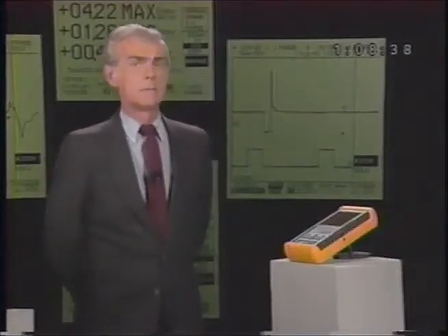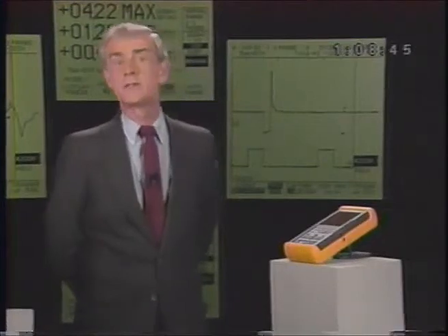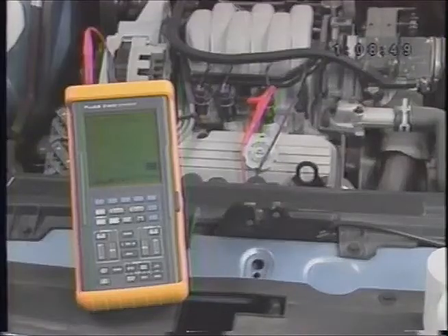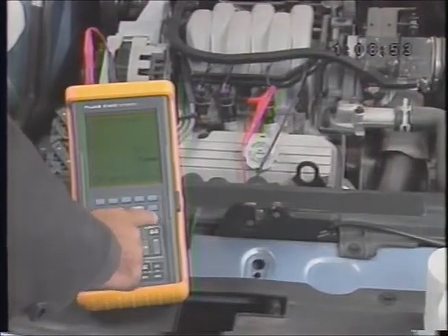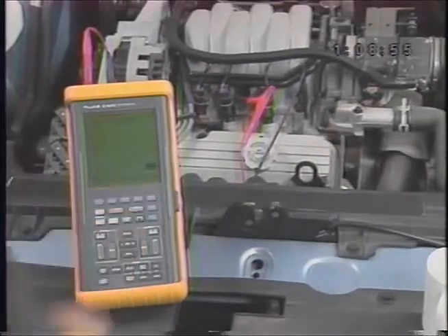Measuring injector on time allows you to check the computer's responses to input changes, such as oxygen sensor voltage or changes in sensor output from the throttle position sensor or MAP sensor. The setup for this exercise will be useful in the shop for diagnostic procedures. Save it to Setup Memory 4.